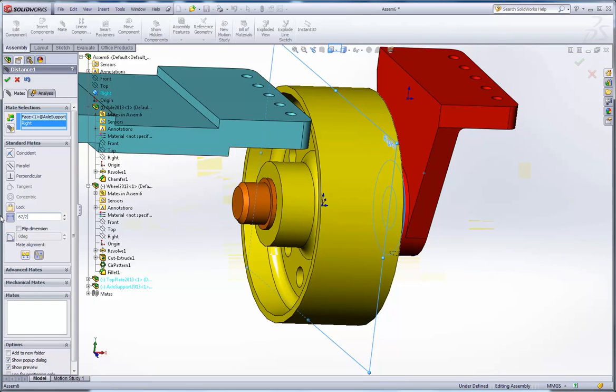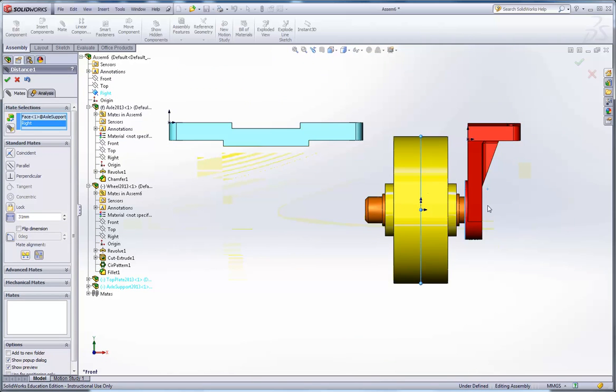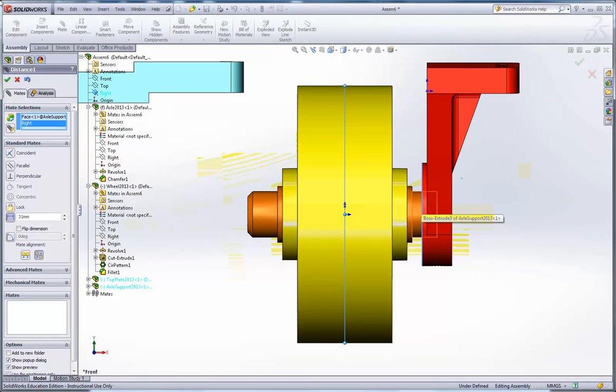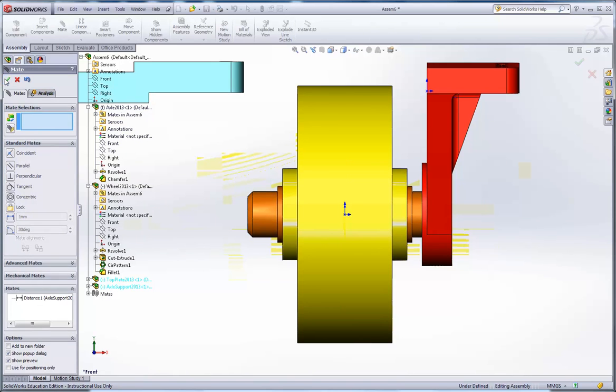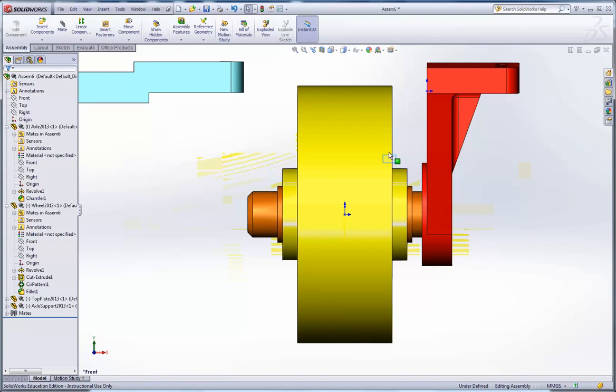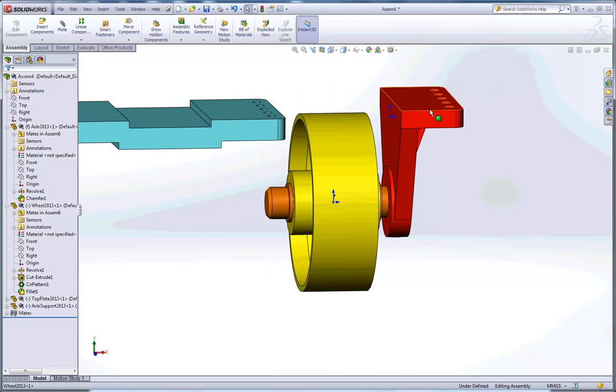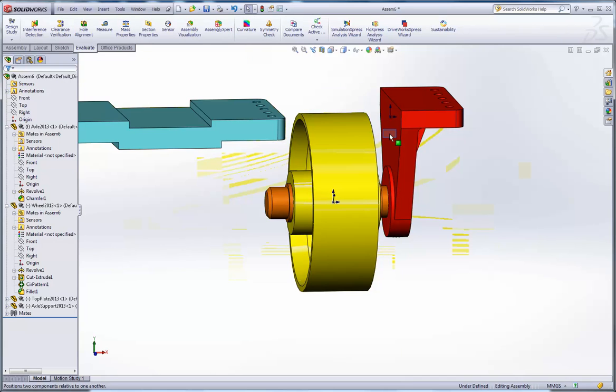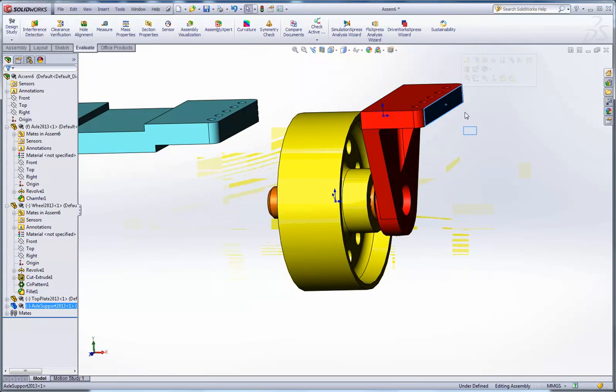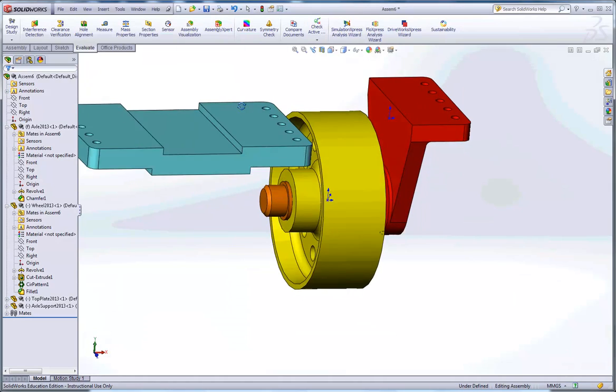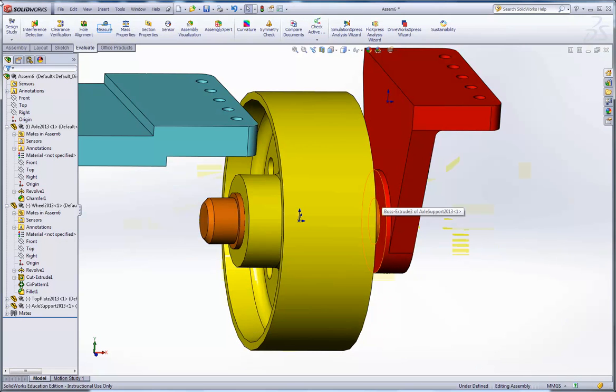I'm going to ask for the front view here so we can see. So I see that there's a certain distance given there. If we look at the drawing, it's actually a little bit closer, and I think the reason being, I'm going to accept that just to show you that you can edit distance mates. If I reevaluate the thickness of this part, you may have noticed, I'll go into evaluate, I selected this face and this face, but that doesn't give me the full thickness of the part because I need to select this face so I get the full thickness of the part.